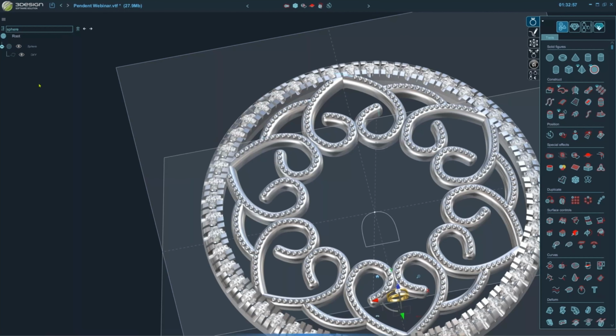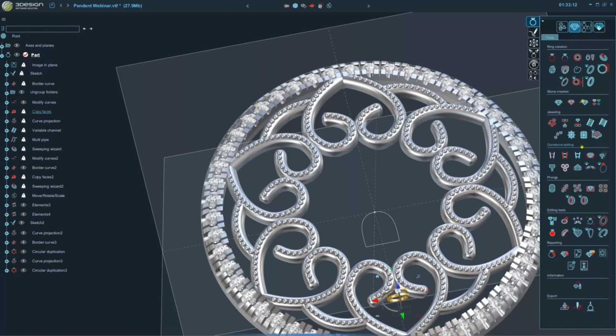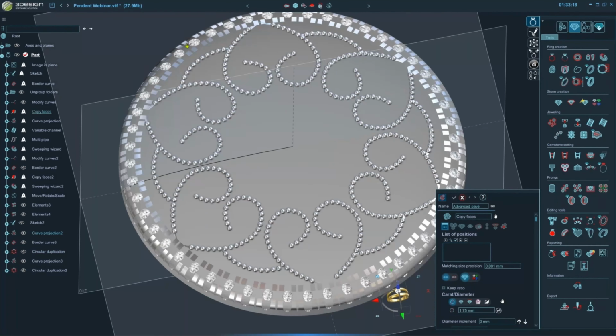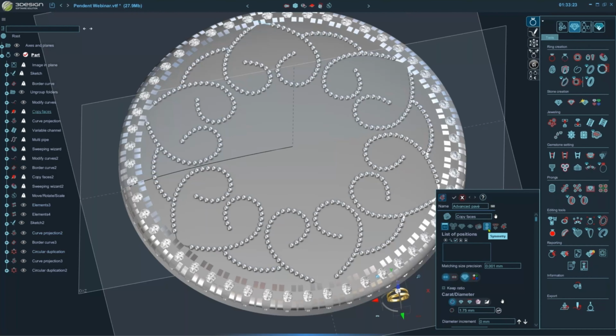So we're going to clear my search here, and we're going to use that same copy face we've been projecting onto. I'm going to create a pave just to easily make my stone positions in between those arcs. So we're going to go to the jeweler's bench with that copy face selected and do an advanced pave. Okay. And because I want 6 of them going around this center axis here, we can use symmetry with axis symmetry. And that axis is going to be the z-axis.